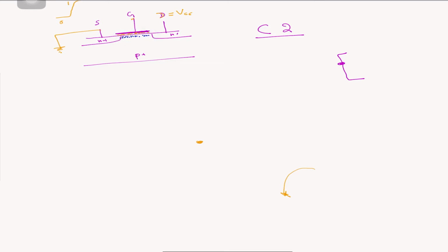Okay, because of the capacitor action, you know, a voltage, electrons accumulate here. Okay, and then when electrons accumulate here, this node is at lower voltage, this is a high voltage, so current flows between drain and source. This is at plus voltage, so the electrons actually start moving this way, and you know that the current is in the opposite direction of electrons, so current is from drain to source.